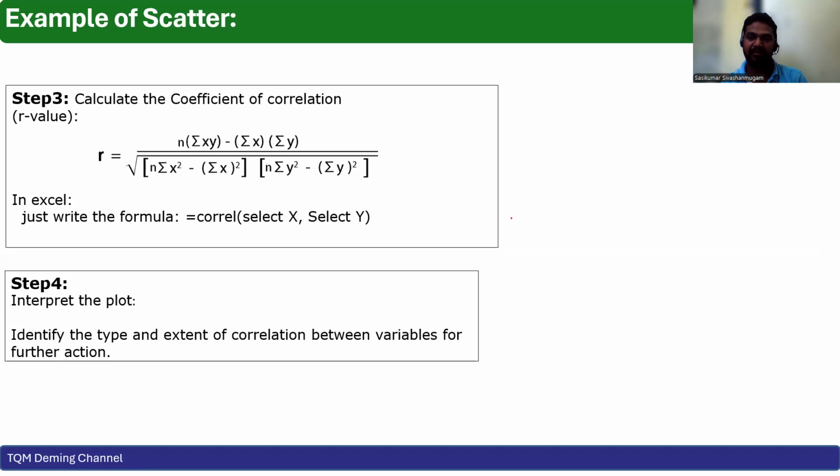What is the oil temperature over the past week at a two-hour frequency? What are the bearing failures over the past year or six months? You can relate the two things and get the correlation of bearing failure with oil temperature.